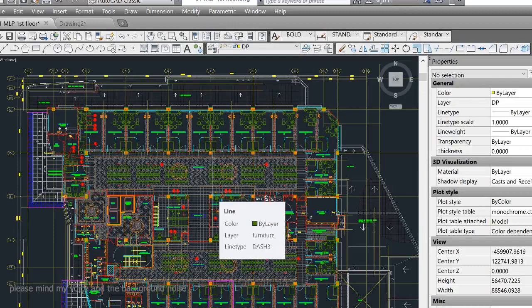And you don't have to set properties for each object. You just determine, for the door layer, that it has to be a dash dash dot type of line. So when you choose that layer, it will be automatically identified as you wish. Thirdly, you can hide or show or lock or unlock a layer. Yes, I did not show you how to lock or unlock.